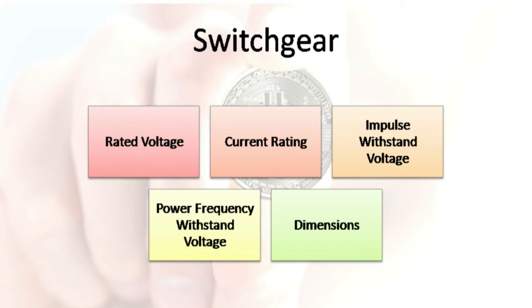maintenance. Medium voltage switchgear can be relatively complicated to spec, as it has a plethora of components such as meters, circuit breakers, contactors, fuses, surge arresters, PTs, CTs, and various relays, etc. You don't need to know all of the intricacies of these components, as usually the manufacturers, and I'm talking about the big ones, will already pick the best ones, and they can tell you whether or not it meets the standards of your local region. What you need, however, is to look at the following properties to see if it suits your needs.